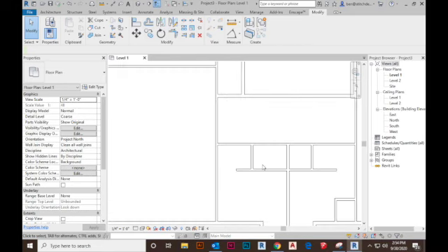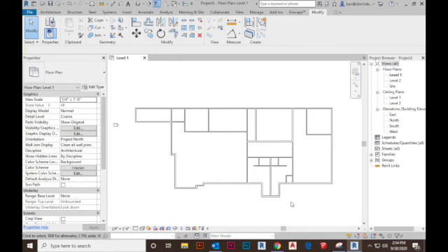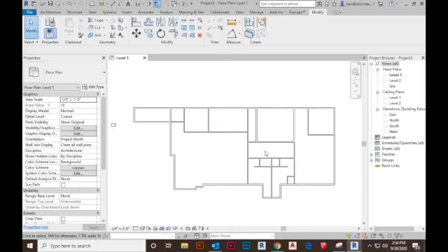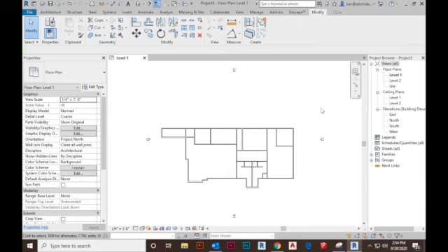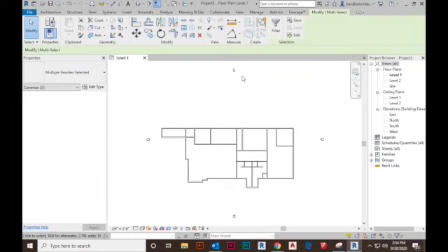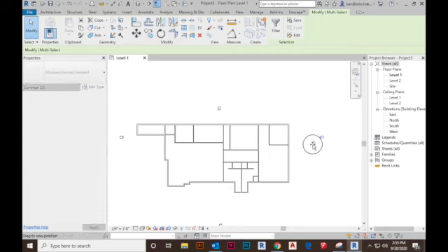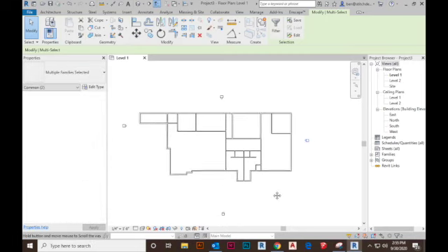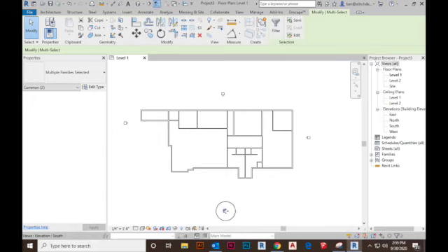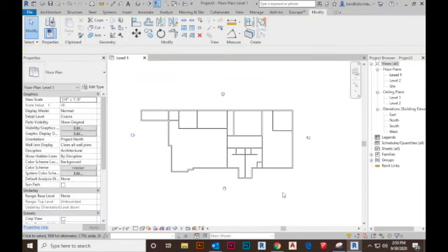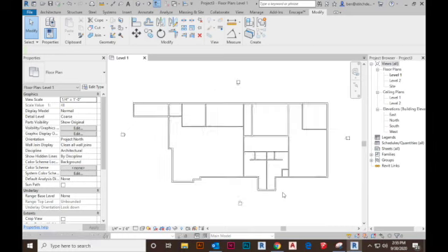We should have everything buttoned up. If we zoom out and use our Zoom Extents tool, let's pull our elevation tags in close enough so that we don't affect how our sheets print. Now let's hit our Zoom Extents command again.